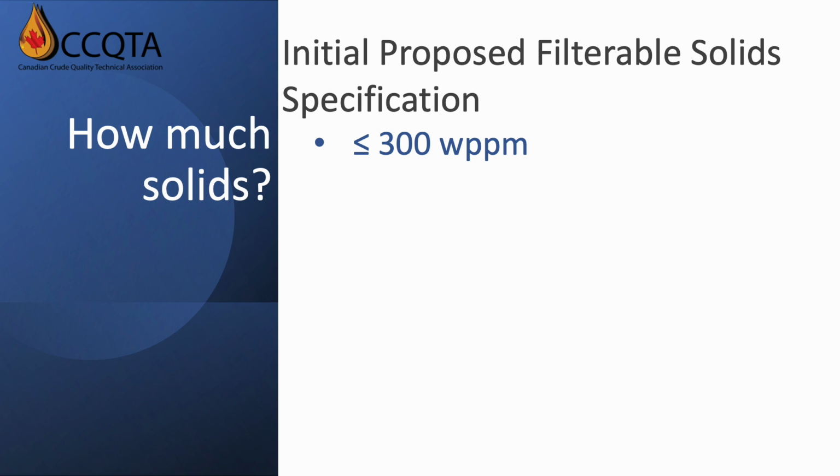On further discussion, refiners indicated that soluble salts should not be included as part of the filterable solids since they dissolve into the salt or wash water and are not responsible for fouling. CCQTA worked with Agate and Bureau Veritas to develop a modification to D4807 to see how much of the filterable